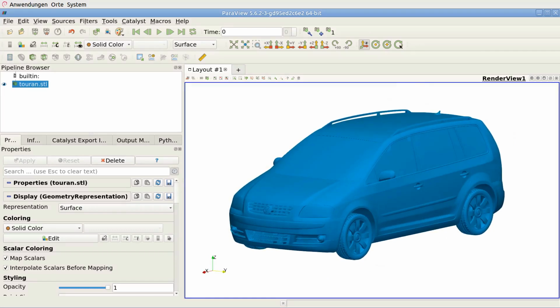You can find such models for example on the GrabCAD website or in the 3D warehouse of SketchUp. In the present case, the 3D model is finally available in STL format. The STL format is very simple and can be exported by all common CAD tools. To create the simulation we now open the InsightCAE Workbench. This is the graphical interface used to edit the parameter sets for a simulation.